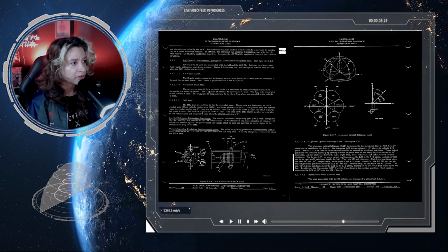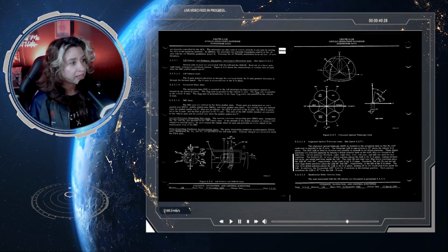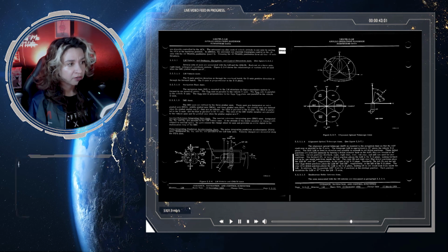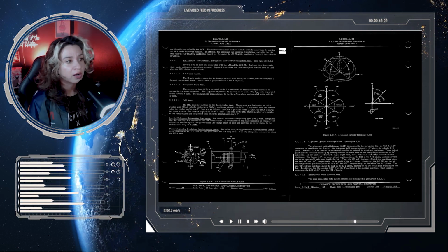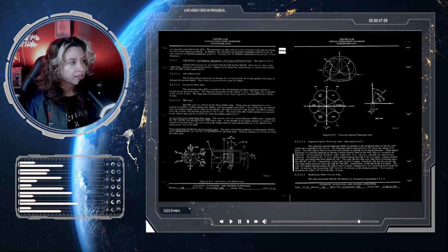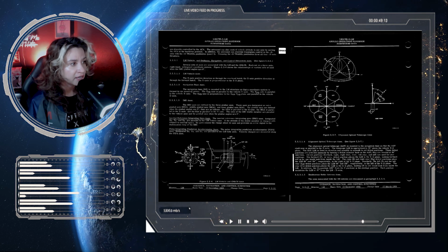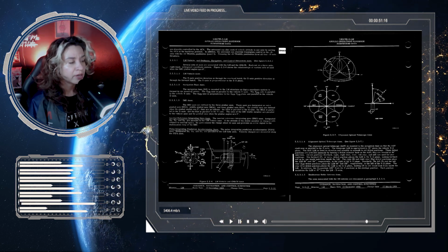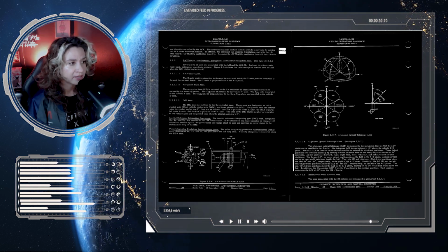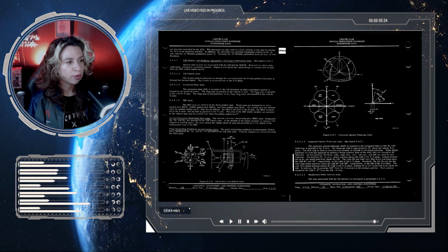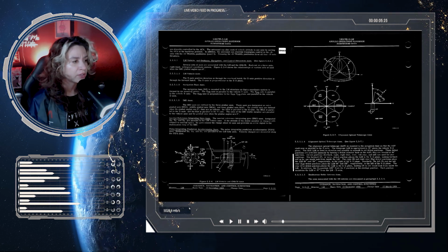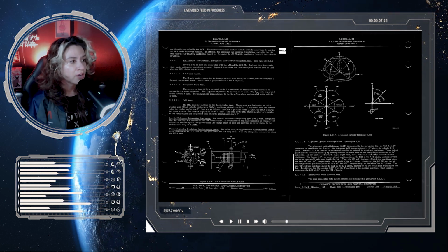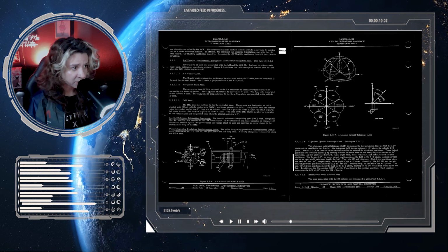Inertial reference integrating gyro axes. The inertial reference integrating gyro, IRIG, axes are designated XG, YG, and ZG, and are parallel to the LM vehicle axis. If the attitude of the stable member is changed with respect to the inertial space, the gyro senses the change.